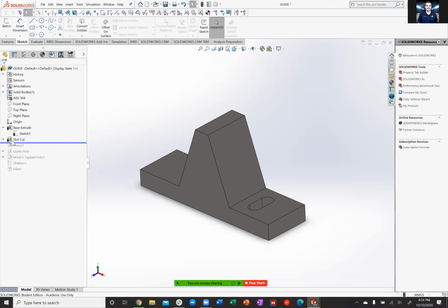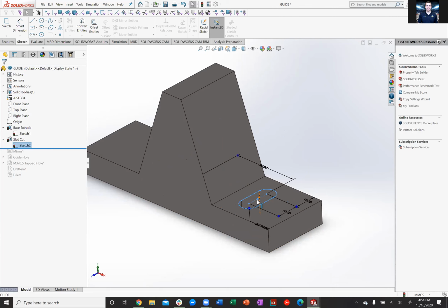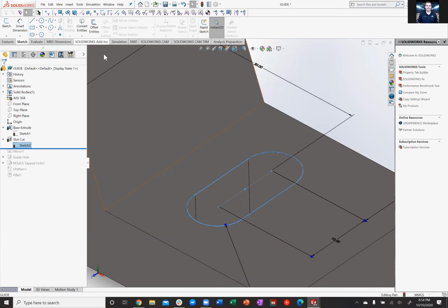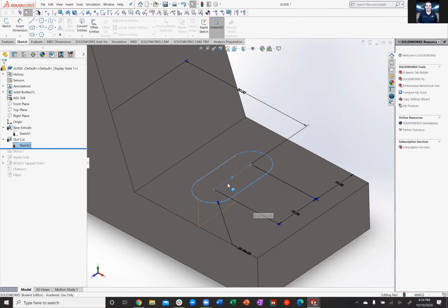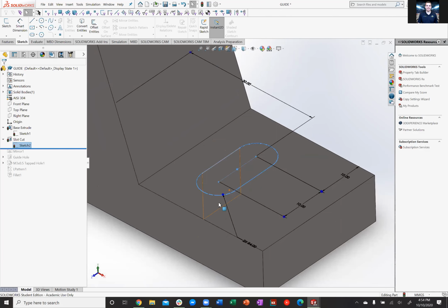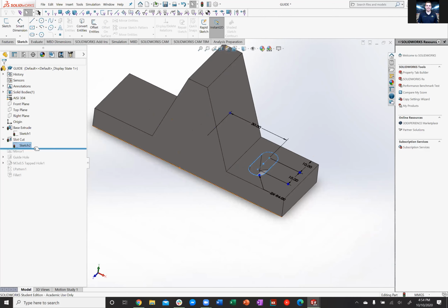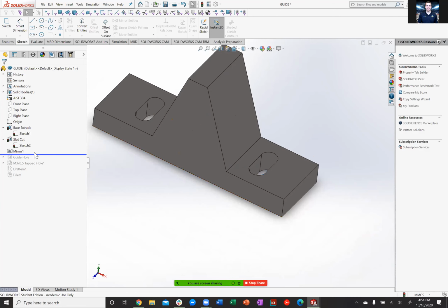The next step here, we used a slot cut. It's just a straight slot. And for slots, you assign the length of the middle here, then you have the radius, and then you reference. For this one, we referenced from the middle point, the origin here, to the center of the slot. That's how we did that. Then we mirrored that slot to the other side.